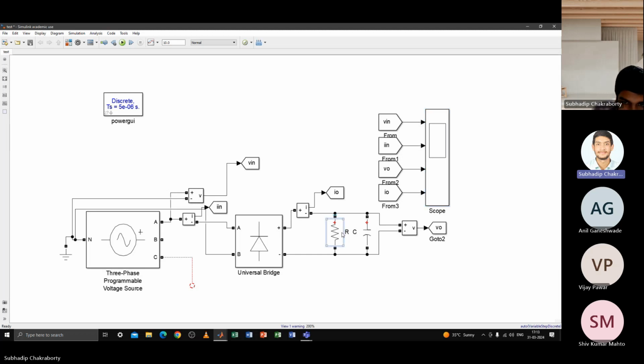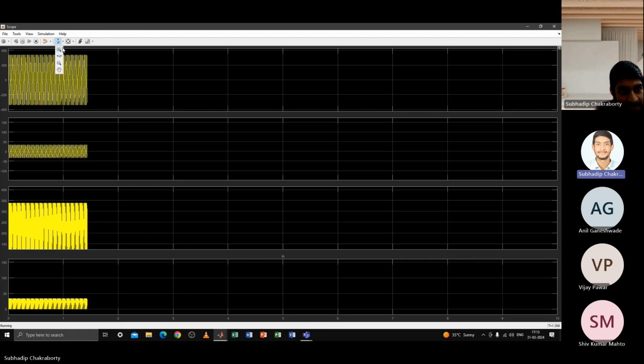It is not unity power factor, because if the capacitor value is somewhat more, then you will experience somewhat leading power factor. So it is possible that a single phase diode bridge rectifier is drawing leading power factor, okay? But if it is only a single phase diode bridge rectifier connected with R load, then your power factor is unity as well as distortion factor is unity, just as I showed you, right?